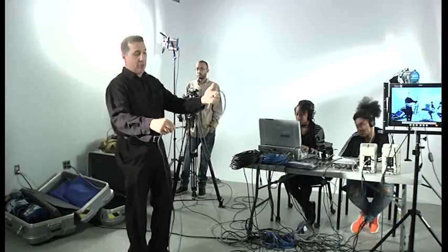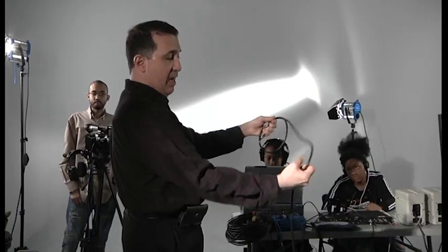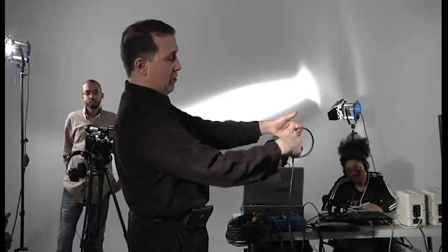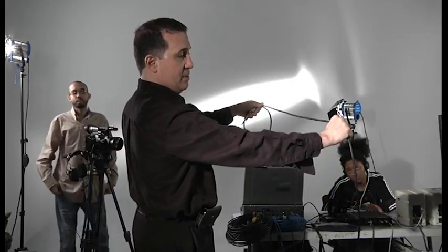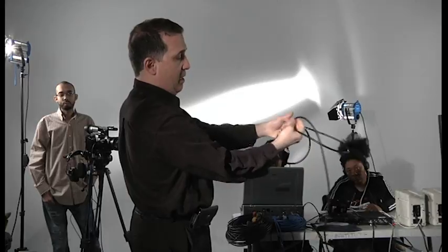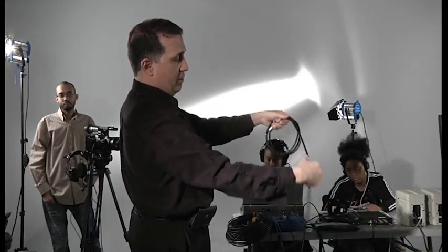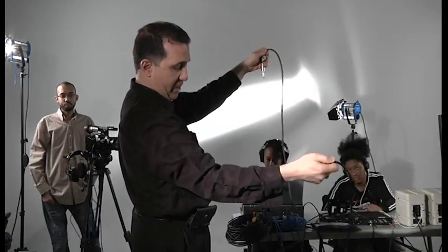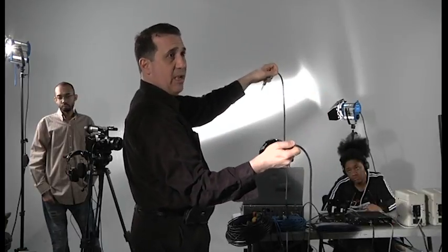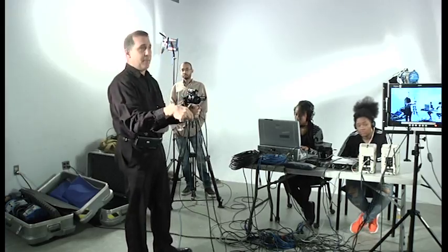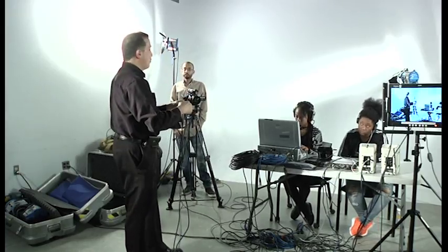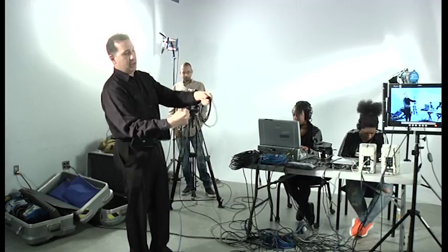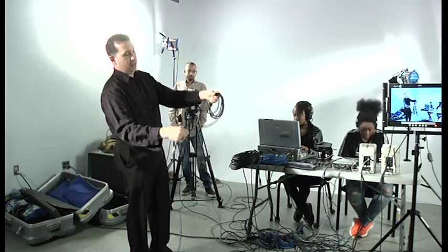Over-under is when you get a cable and you wrap it over once, and then you find a method of taking that second wrap. Usually what I encourage everyone to do is to go over once, and then with your hand like this, put your wrist up in the air, and go under. And then you go over, and then you go under, and you go over. What that does is that when you spool your cable out, you have very few kinks. Yes, you may end up having a kink every now and then, but you don't have as many because you wrapped it correctly. So I'm going to go over, under, almost over, under there.